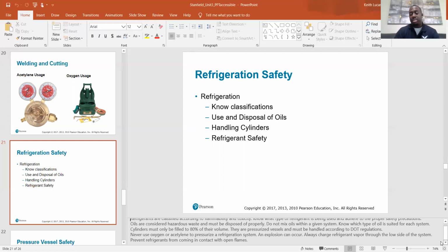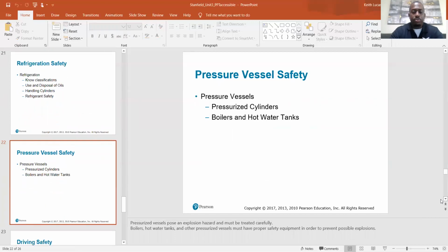Now, let's say you had that cylinder 100% full and it's nice and cool. All right, no issues. But now it's significantly hotter in the day, and that temperature went up, so now that pressure is going to go up, and we don't have any more space to compensate for it. You're going to blow the relief valve on that cylinder, or even worse, possibly explode the cylinder. So you need that extra space to account for expansion. So that's why you don't fill cylinders more than 80%. You fill it up to 100%, you don't leave yourself any wiggle room.